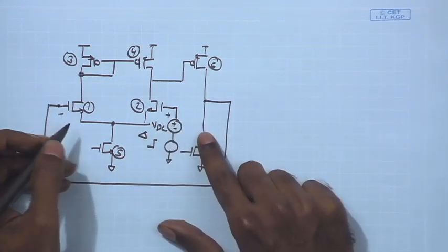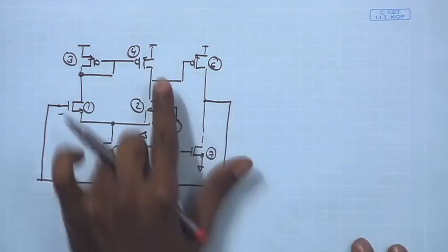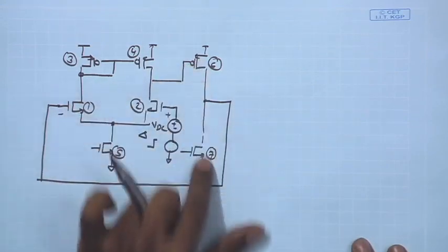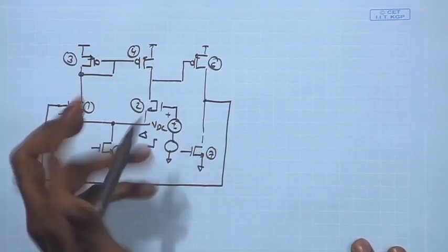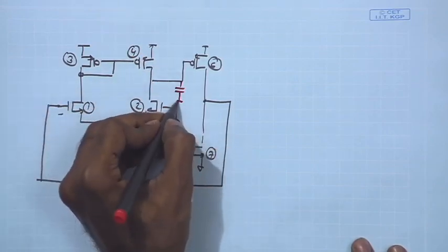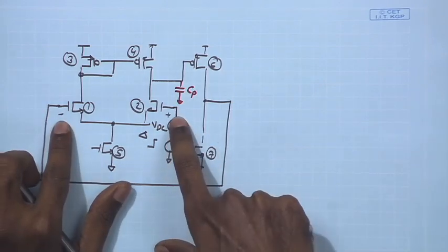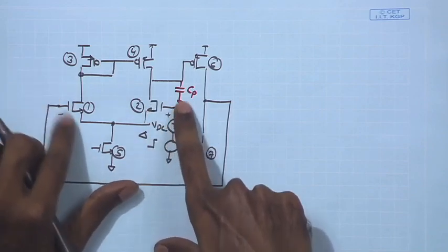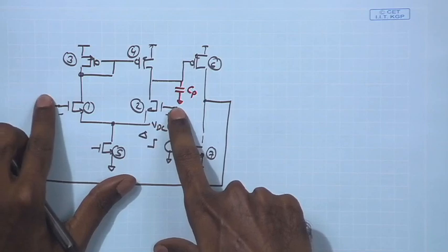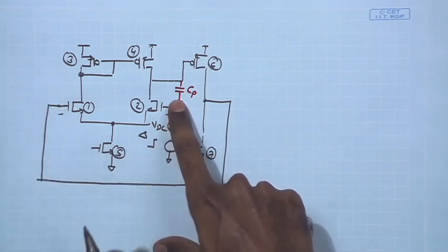At least at this node, of course, we have some parasitic capacitances coming from the common source stage as well as the parasitic capacitances contributed by the transistors in this stage. So, I have some effective Cp over here, and when we apply a delta voltage over here at t equal to 0, we are creating an effective difference between the gate potentials of M2 and M1. We are increasing the gate potential of M2 with respect to M1.